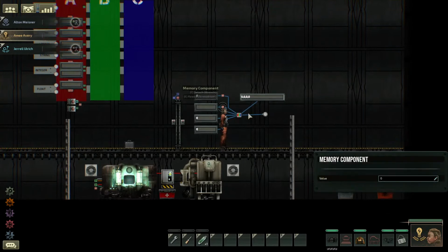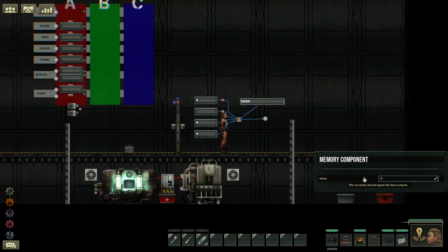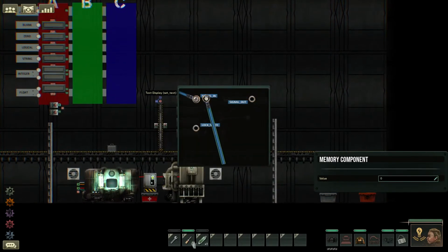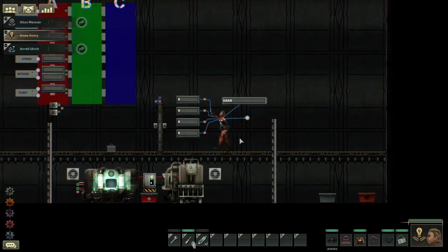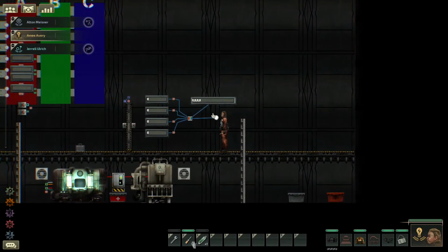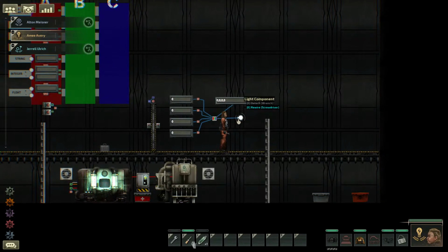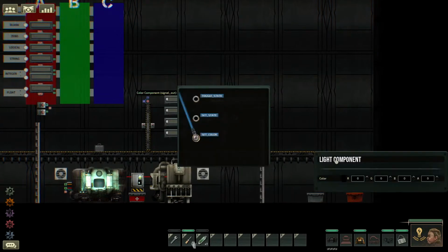You gotta delete that door, it's gonna give me a tumor, right? Oh, wait, it's not the 0 value that I did wrong, it's the wiring that I did wrong. Hang on here. So we put the, okay, so we get 0, 0, 0, 0, okay? No matter what the input is to this set color input, as long as it's a value above 0, it's going to have some intensity, and above 255 has no effect. If you were to put 1000 and 0, 0, 0, 0, you'd still get the same red that you would get if you put 255, 0, 0, 0, 0, right?